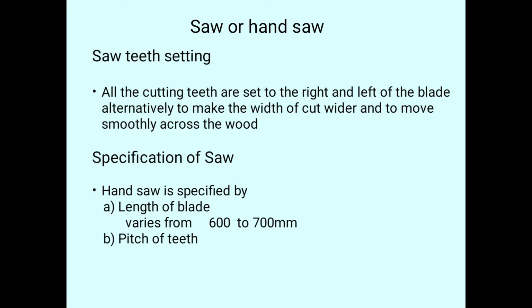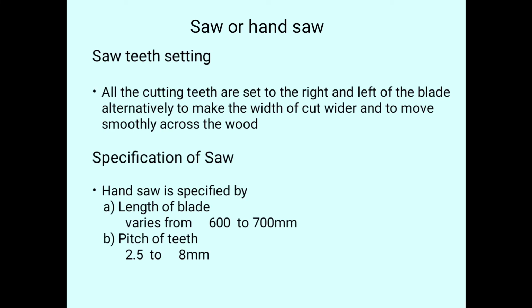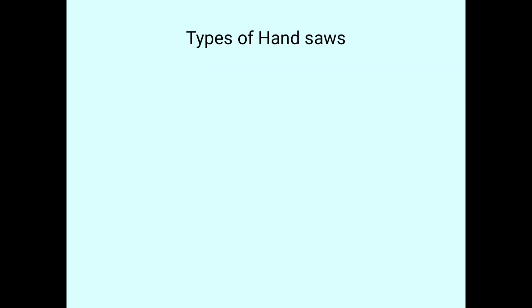Second, the pitch of the teeth, which varies from 2.5 mm to 8 mm. Based on these two specifications, we can select or specify the saws.